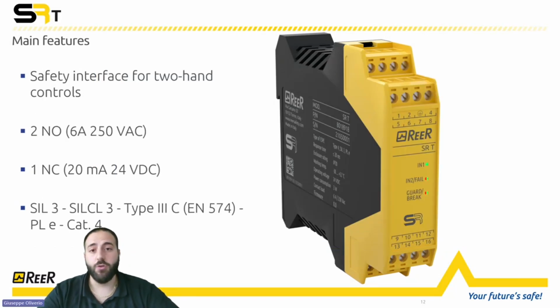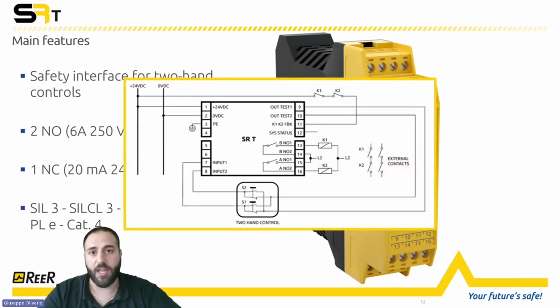In case of a two-hands control based on the EN574 type 3C, we can use the SRT that is used for a two-hands control with switching contacts. And again, in this case, we have specific output tests with specific inputs, and then you can control the logic of a two-hands control. And the interface itself will check if you press both contacts at the same time. So it will check also the simultaneity of the contacts.